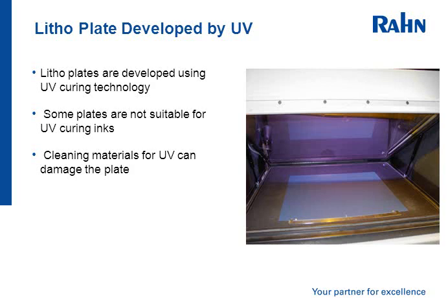The litho plate is also produced or developed by UV, and therefore the materials on the plate are UV cured and therefore sometimes very compatible or damaged with some of the aggressive monomers that may be used within a UV formulation. Some plates are not suitable for UV curing inks, and normally the printer will have to talk to his plate manufacturer, and many plate manufacturers have UV recommended plates. Cleaning materials for UV can damage the plate.